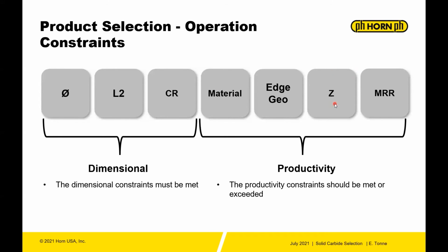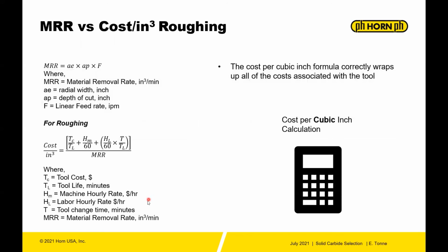Number of flutes, how that ties in is if you have a very sticky material that produces a bigger chip, then you don't want to select a tool with a lot of flutes if you plan on doing semi-finishing to roughing with it, because it will just clog. And then your MRR, you have to think about that, put pencil to paper and figure out what your MRR needs to be and whether that tool can meet that.